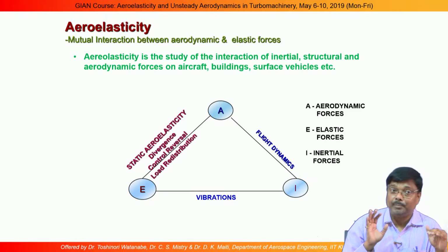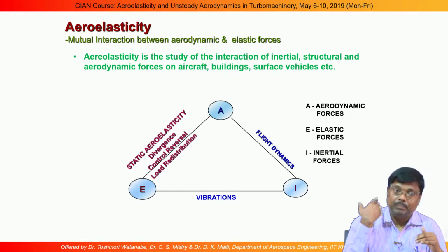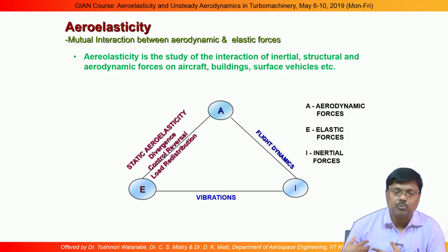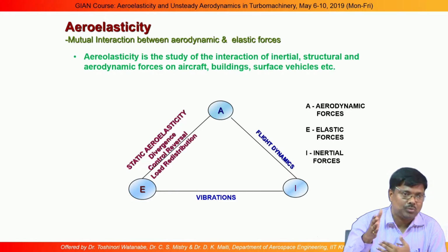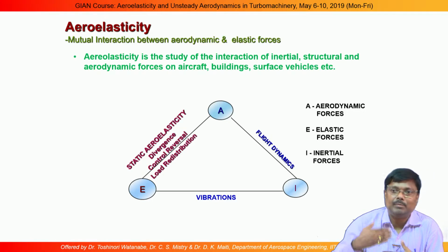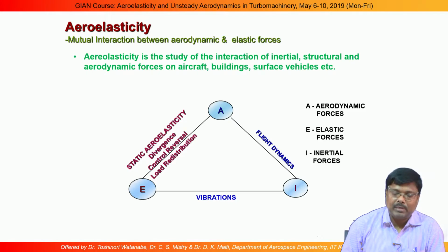I am not equating the forces in that direction. If I equate in the forward direction, there will be the thrust force and the drag force, and the forward force. These forces have to be balanced, then only can the aircraft have a constant velocity or constant acceleration forward motion. Those are the maneuver conditions we can have, because for a transport aircraft we usually do not need many different types of maneuvers.